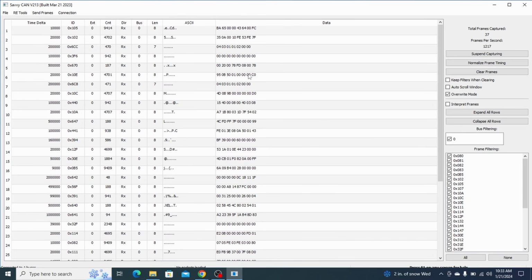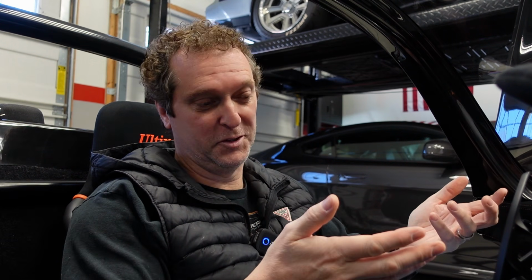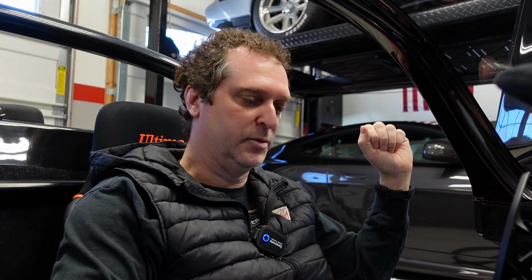The one I love to start with is something that is super easy to manipulate. Something, a switch, something super easy, like a brake switch. A brake switch is simply on or off. Super easy to control. Obviously, just put your foot on the brake. You can manually control it, and you can watch the data in real time since, again, you're in control. It makes it easier to kind of call out the data bit that's being changed when you hit that brake switch.